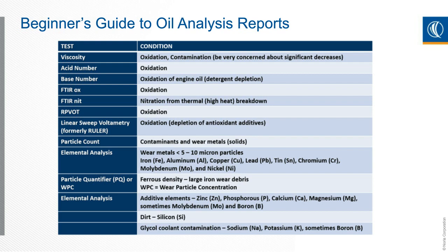RPVOT stands for Rotating Pressure Vessel Oxidation Test. So oxidation is what we're looking at here. As your oils get used up in service, your additive levels are going to change. Antioxidants are going to go down, and that's going to cause the RPVOT values to go down as well.